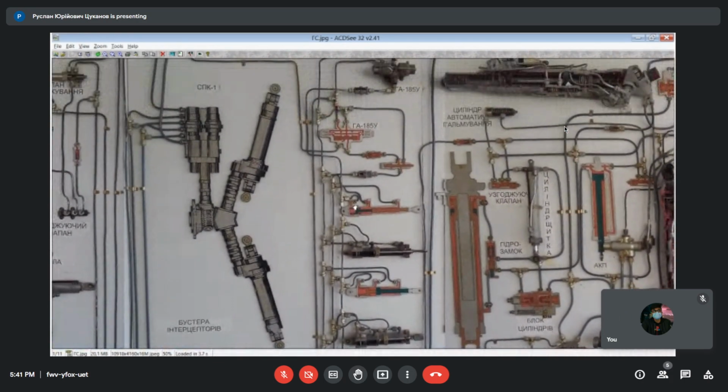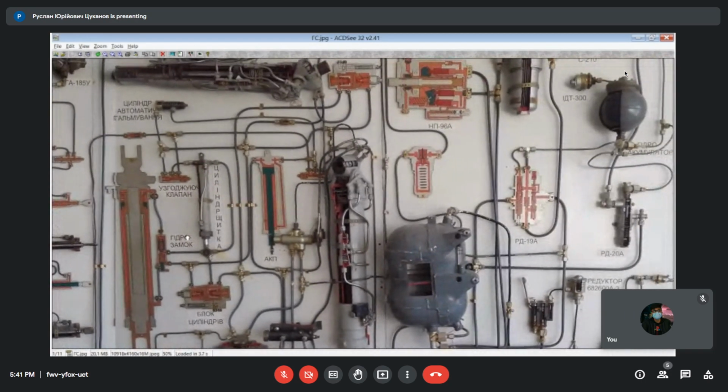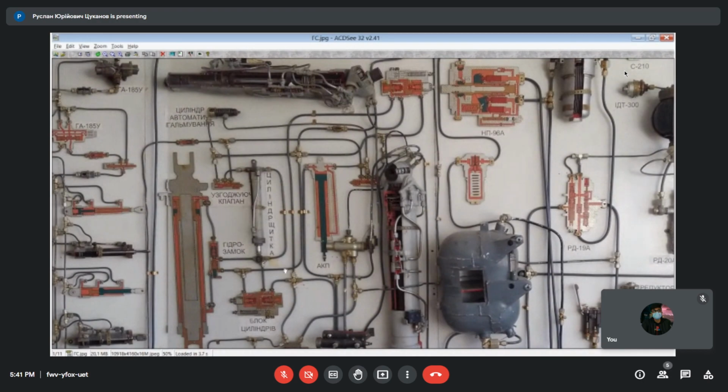It's possible to mention the essence of these sequence valves. Their idea is to prevent damage of flaps when the wing is retracted and some portion of the flaps entered inside slots and fuselage, and it prevents fuselage damage if the pilot accidentally tries to extend flaps when the wing is retracted. So it's a mechanical sequence valve which prevents accidental wrong motion.